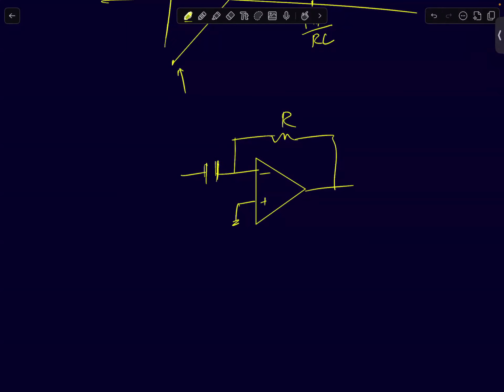So what can I do? By looking at this circuit, can you guys say can you do something here? Why is this gain blowing up at high frequencies? There are two impedances that are responsible. This impedance and this impedance, right? The ratio of the gain of the circuit from input to output is simply ratio of this impedance to this impedance. At high frequencies, this impedance is becoming close to 0. See, the capacitor is providing lower and lower impedance. All I need to do is ensure that the capacitor impedance is finite after a certain frequency. So just add a resistor in series.